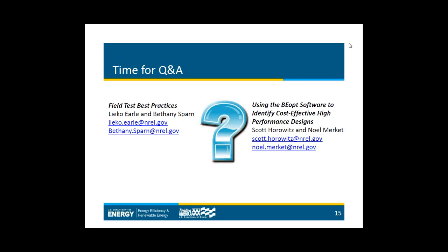Those rates can be tiered, time of use, or both tiered and time of use, and it defines things with PV compensation as well. Alternatively, if you can't find the rate that you want, BEopt has a built-in interface so that you can quickly drag your mouse and define periods for time of use as well as tiered rates. You can even enter an 8760 hourly real-time pricing utility rate if you wanted to do that. So it's got full flexibility for defining utility rates.